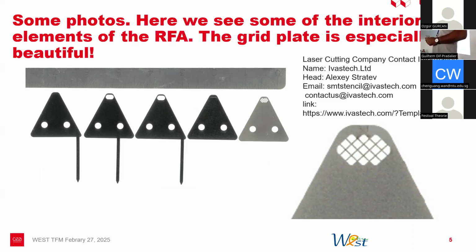And they typically have 0.5 millimeter spacing between them, so it doesn't leave much room to install a probe. So we had to cut some of these PFUs a little bit wider than normally. So we have slits of about, if I remember correctly, 6 millimeters between the PFUs. So our probe had to be no more than 4 millimeters thick. So this was quite a challenge for our technical staff.